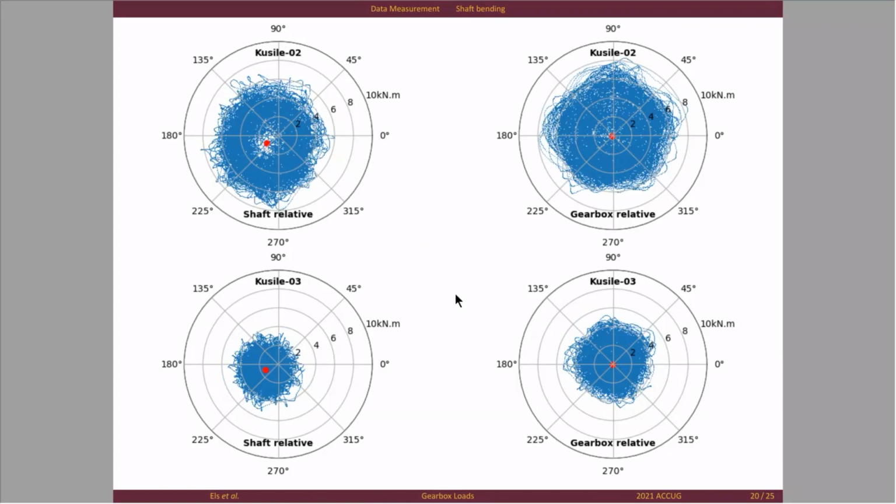And I think for a gearbox guy, this is worrisome, because we've measured close to the hub. So the bottom bearing of that gearbox sees a fairly large bending moment on the shaft. I don't know what they're designed for, but this is quite high.